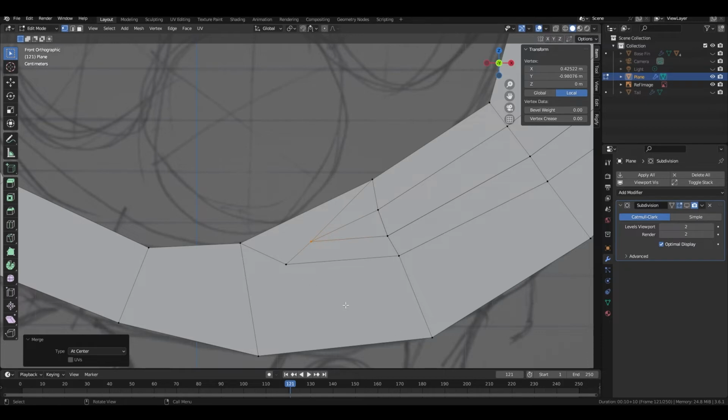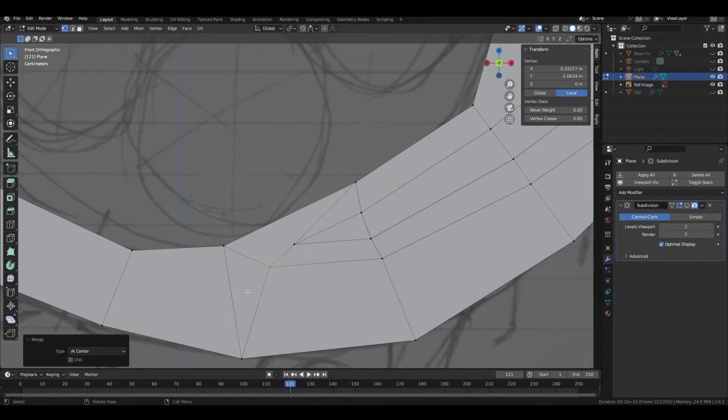We've also unfortunately got a 5-sided n-gon here as well. And I think probably just the simplest thing is to cut it here with the knife tool again. So cut to there. And often what you'll find is that it makes a new vertex very close. So it's often quite a good idea to just go in, if you're at all uncertain, and just merge what you think are the single vertices. So now we're much better.